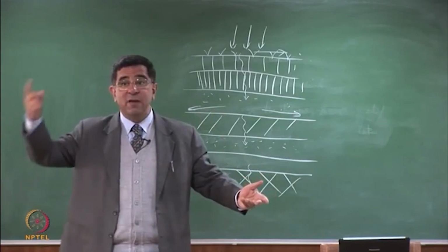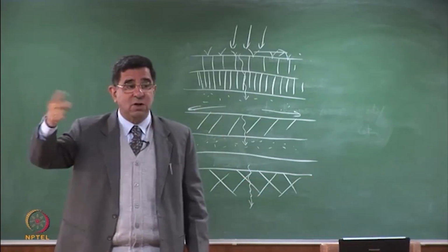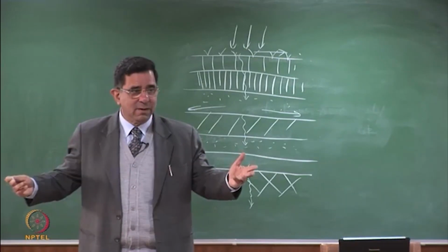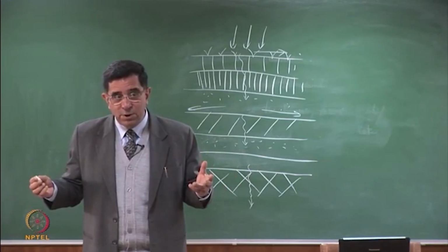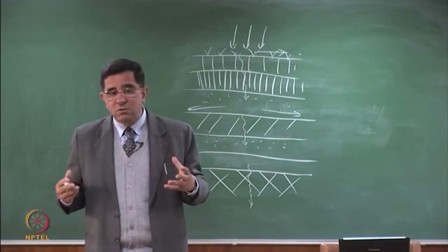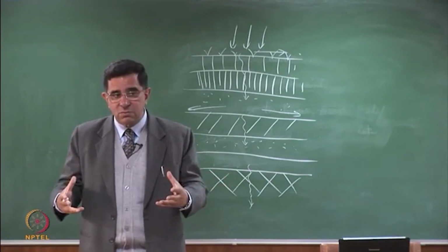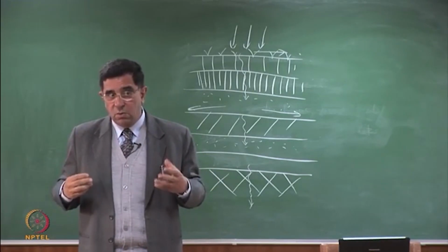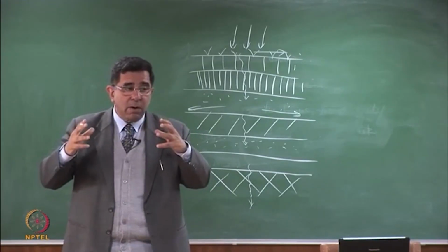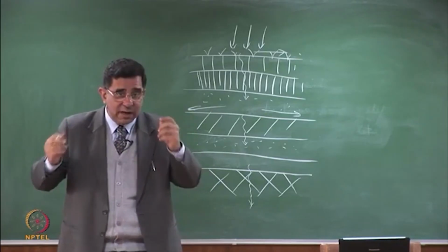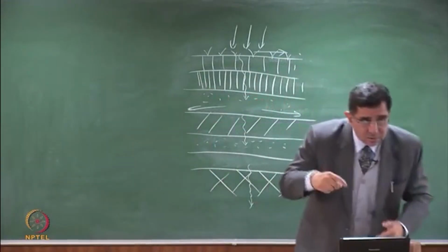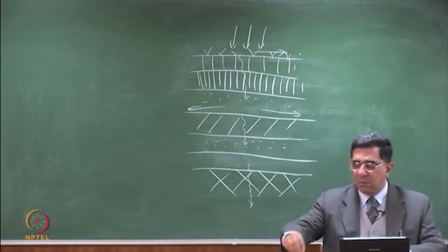So you say, no, rain is coming. Professor Datta gave a lecture, no, you shouldn't allow the leachate to form. Trucks will start lining up. You can't stop it. You can't stop putting your waste, and you can't have a temporary cover on the site all the time. In the monsoons you can be actively geared for this, right? But what I'm trying to say is, it's the active part of the landfill which creates the leachate, and that is what you have to understand. That is the message which is normally lost in this water balance which we talk about.